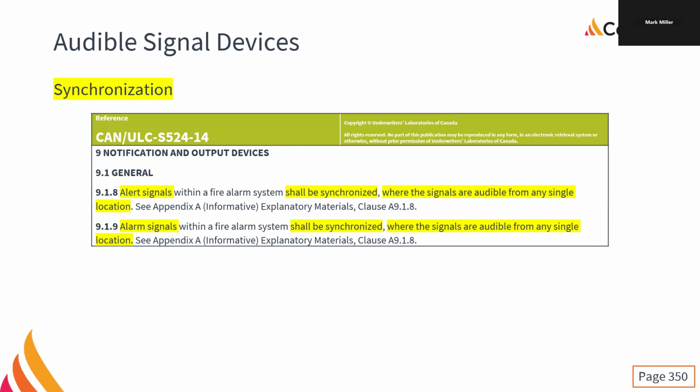Unbelievable. Mircom and Notifier are good at synchronization. I just really hate how it gets done. Mircom, I'm not a fan of the Mircom systems because it's not as efficient and clean as it could be. You have to install synchronization modules to get them to synchronize properly, which I don't get because why is that not just installed in the panel right from the factory? It doesn't make any sense.